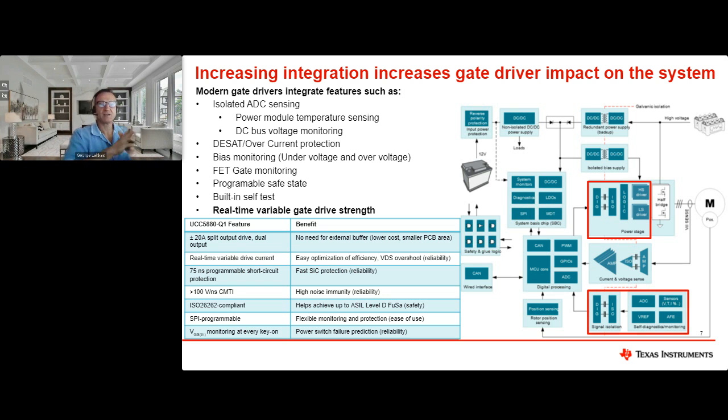For example, we have 10-bit analog-to-digital converters inside the gate driver, anywhere from 2 to 6 depending on the product, that you can use to sense anything you want, but most importantly the power module temperature and usually the DC bus voltage. You could also use them to sense the phase current or even the internal voltages on the gate driver itself.